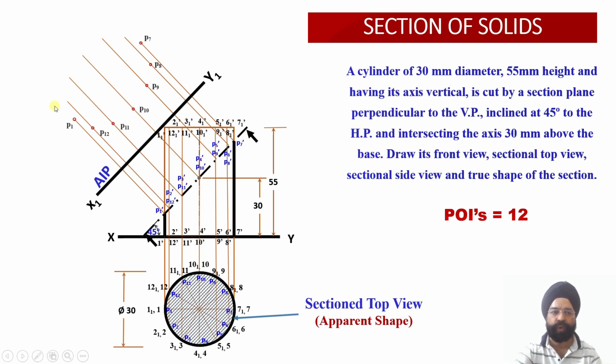Now next we move on to these points. To start with this, you see I have marked both of these points simultaneously. This point is point number 2. This point is point number 6 over here. Just see, this is the distance of 2 from XY. I measured this distance of P2, and the same is the distance over here corresponding to P6. So P6 and P2 have the same distance from the XY reference line. Just see, P2 and P6 have been shifted simultaneously.